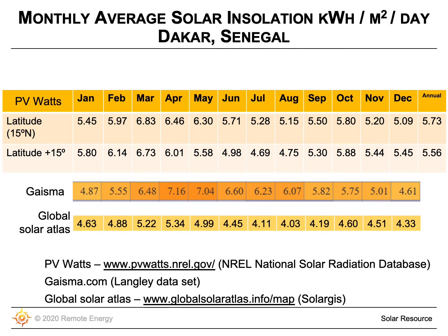Turns out that the Global Solar Atlas data here is not giving us solar insolation values at all. What they're actually telling us is how many kilowatt hours could be produced by a 1 kilowatt PV array. So it's a slightly different data set altogether. This is looking more at energy production instead of solar insolation. So again, just showing different ways that data is presented. Very important to understand what you're looking at.